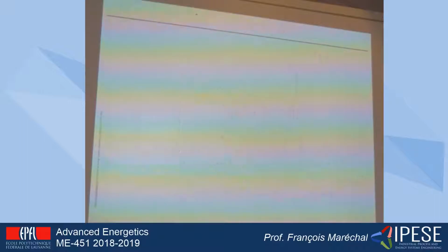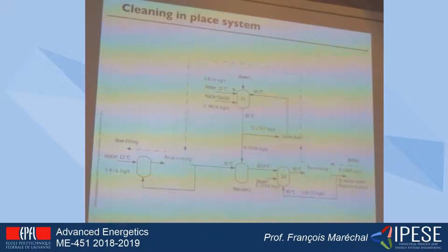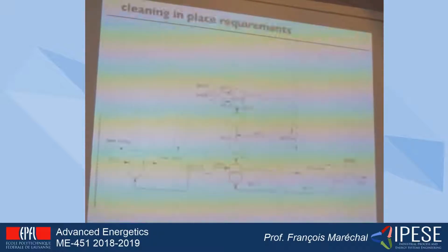So for example, here the goal was, if I have to produce steam, then I realized that the steam is part of the process, meaning that the steam has to enter from outside, be preheated, and reach the steam temperature. So evaporated and reach the steam temperature. That means that it would be a cold stream from 20 or 15 degrees C to the saturation state plus the vaporization at the pressure at which it is injected here.